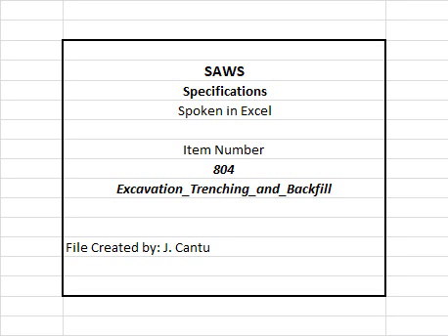4. Dewatering. Prevent surface water and subsurface or groundwater from flowing into excavations and from flooding project site and surrounding area. A. The contractor shall not allow water to accumulate in excavations or at subgrade level. B. Remove water to prevent softening of foundation bottoms and soil changes detrimental to stability of subgrades and foundations. C. Provide and maintain dewatering system components necessary to convey water from excavations. D. Convey water removed from excavation and rainwater to collecting or run-off areas away from buildings and other structures.